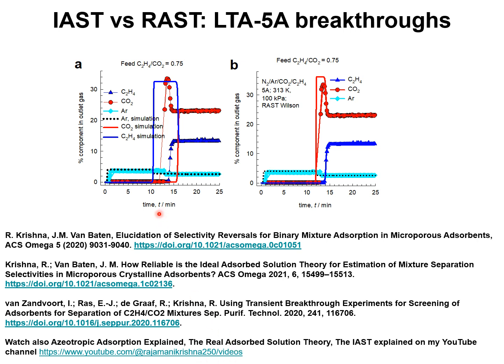If we incorporate thermodynamic non-idealities and carry out breakthrough simulations using the real adsorbed solution theory with the fitted Wilson parameters, the breakthrough simulations shown by the continuous red lines and continuous blue lines are in good agreement with experimental data. 2 important conclusions that emerge from these presentations are the following.